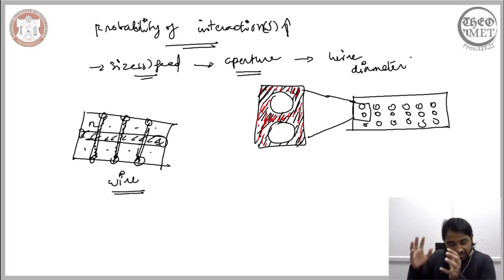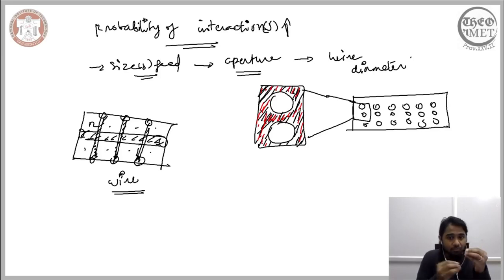So in the case of the realistic screening table, what you essentially have is, we use wires and meshes in order to build these perforations, and depending on the thickness or the diameter of this wire, the section that separates these perforations varies. Therefore, this needs to be included while we are formulating or taking a probabilistic approach for the interaction.